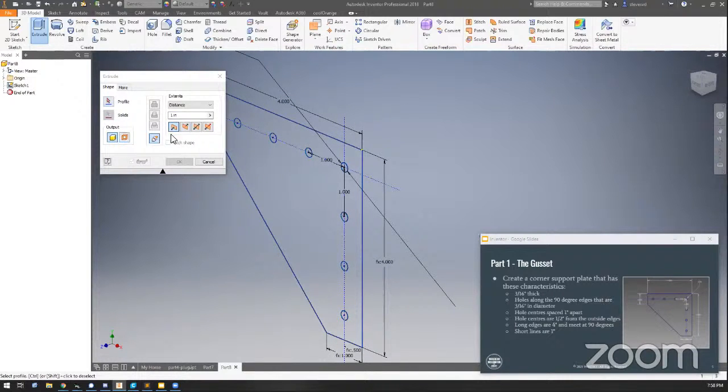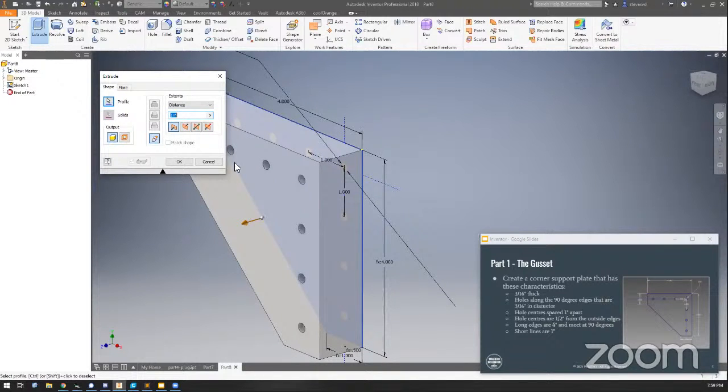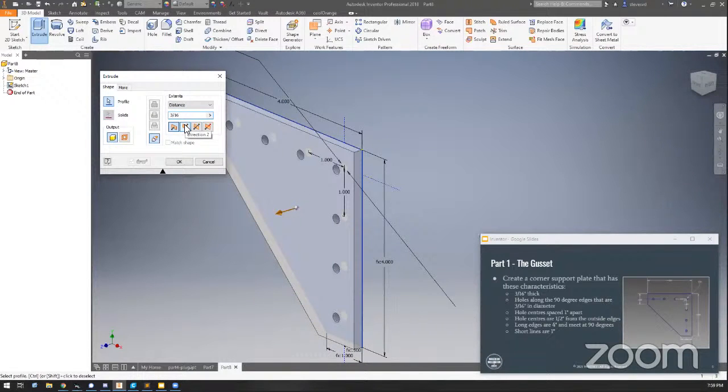and then that isn't selected anymore. You see this dialog actually looks kind of similar. It's saying, select me a profile. In the rectangular pattern dialog, it says, select me a piece of geometry. So it's kind of asking you questions that you fill in. So I'm going to say, select this profile. And it's going, great. Now tell me how big this needs to be. Well, that's 1 inch thick. That's a pretty big gusset. So instead, I'm going to make it 3/16 of an inch. And you see now it's created me that plate.